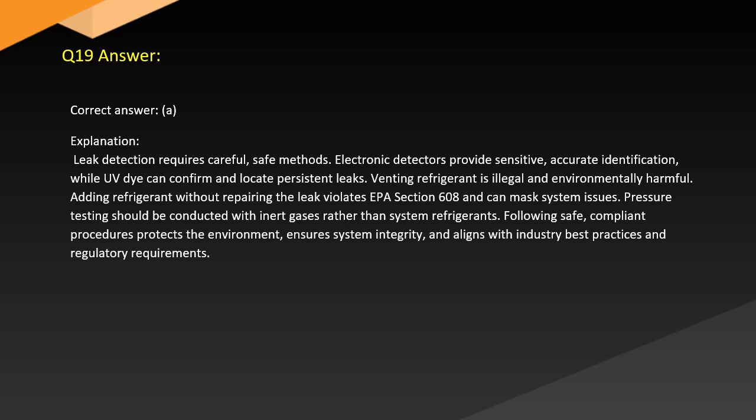Pressure testing should be conducted with inert gases rather than system refrigerants. Following safe, compliant procedures protects the environment, ensures system integrity, and aligns with industry best practices and regulatory requirements.